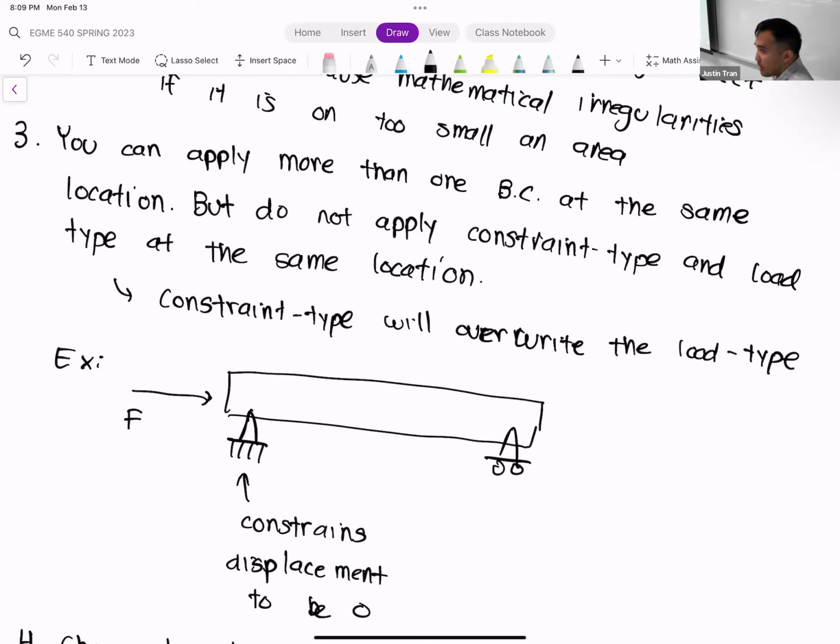Yep, you could. Yeah, so there's a module in ANSYS that does fatigue life analysis, and so you can factor that in. You can put in, this part has been through such and such number of cycles, and then that can affect the structure of it as well. Yeah.